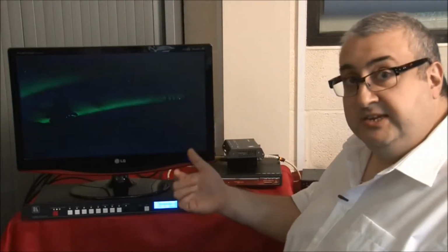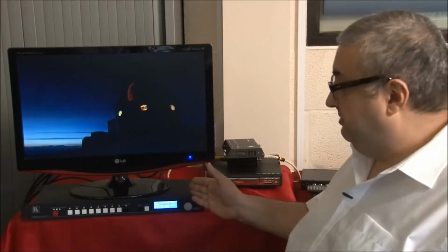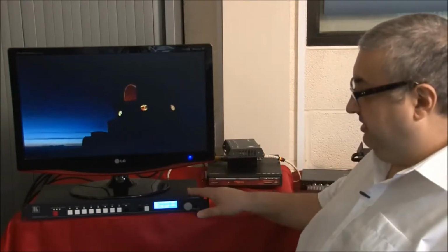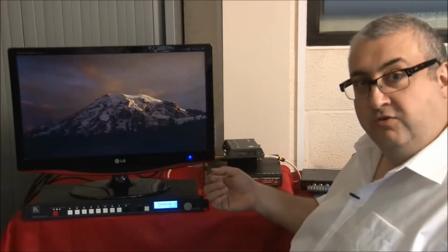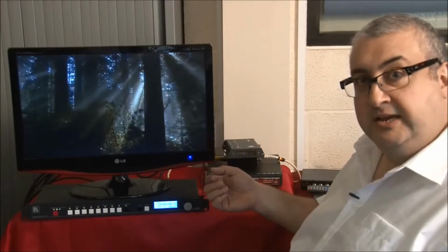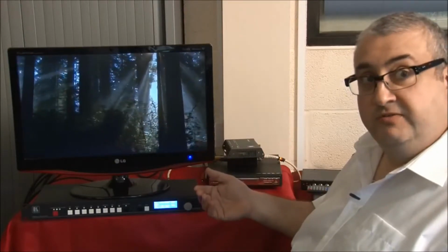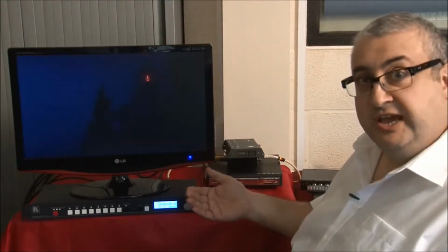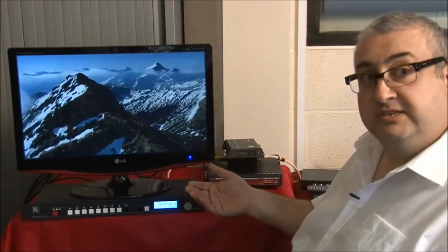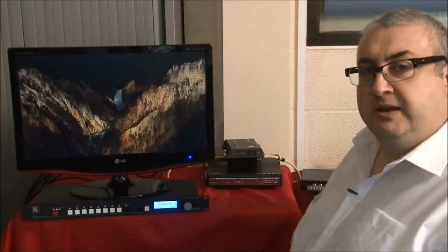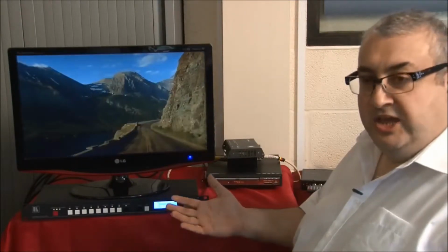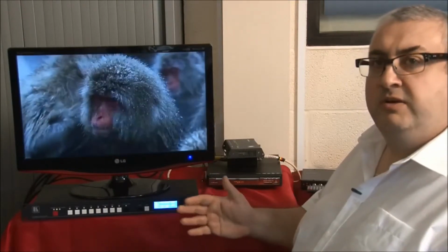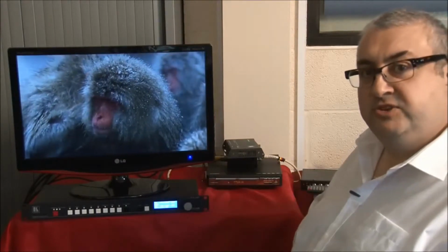The first is to give an external Genlock sync or Genlock reference to VP-794. That tells VP-794 to maintain a constant output which is locked to the Genlock reference, and that's the correct way to get clean switching if you're in a television studio environment, a concert environment, or some other big event, maybe where there are television cameras and there is a Genlock sync run round to different devices. But what about if I'm in a smaller environment? Perhaps I'm in a house of worship or some education environment or something else where I don't have Genlock sync and a full broadcast infrastructure.